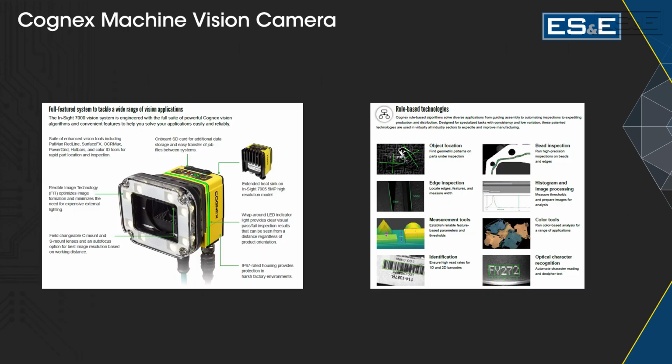That's crazy. So getting off of IO-Link, this will be connected via Ethernet, going back to your control system. But yeah, so a Cognex or any type of machine vision camera, this will be reading your barcode, detecting that the data coming out is correct, making sure it's in the right spot on your plate. You know, it's got all different types of tools we can add on. Nice. Okay. So no issue reading this really small barcode? Nope, not at all. You can read any kind of barcode you can think of. Okay. All right. That works.